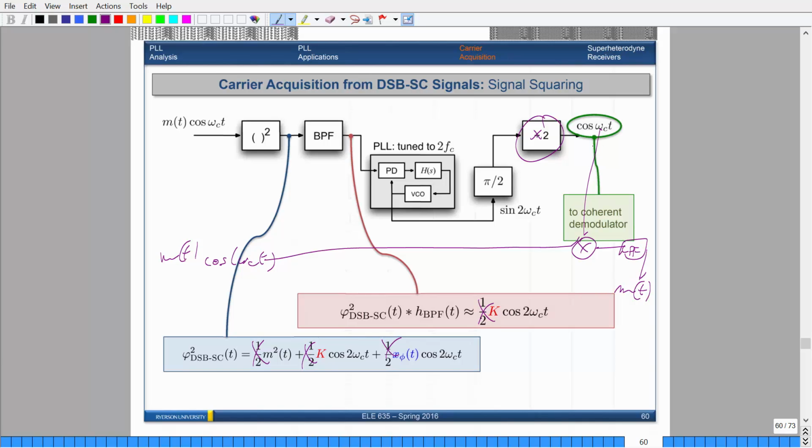So that's the whole point here, to actually extract the carrier from what was suppressed from the beginning. So apply a squaring function, do a bandpass filter, and get a phase lock loop in there to ensure that your carrier frequencies match, even though there might be a little bit of tolerances or errors. You'll do a phase shift to get cos, and then you want to multiply by 2 to get rid of these gains of a half here.